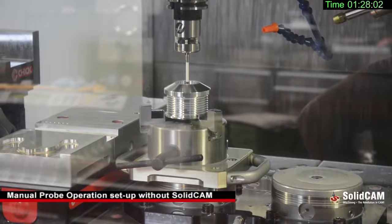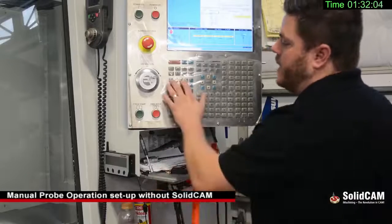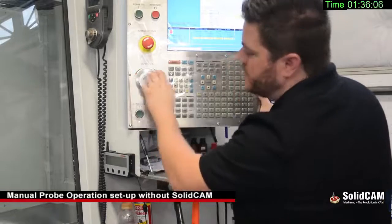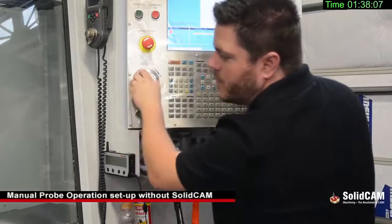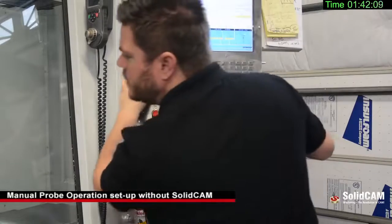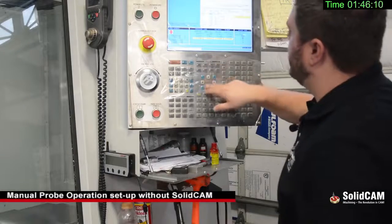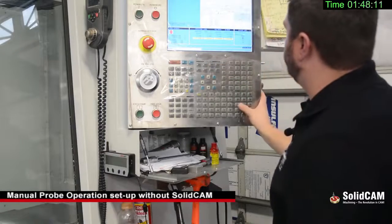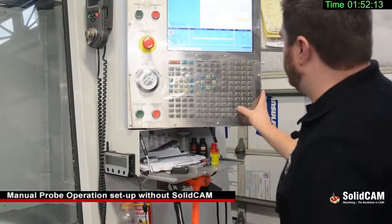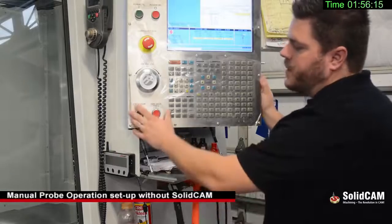Now all we have left to do is to find the Z. Now we're going to move our probe out of the pocket and over onto right above the top plane of the part. And then we're going to record the Z using a single surface. So now we're just going to go back here. We're going to do a single surface. Come over. We're only going to travel in the Z distance. So I will tell it to go roughly 200 thou, and then we'll go cycle start.